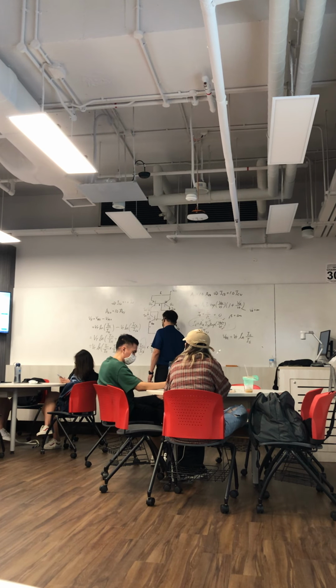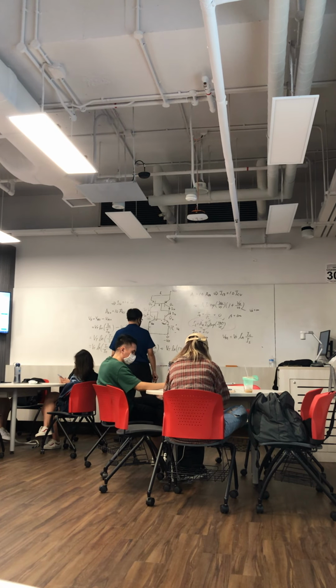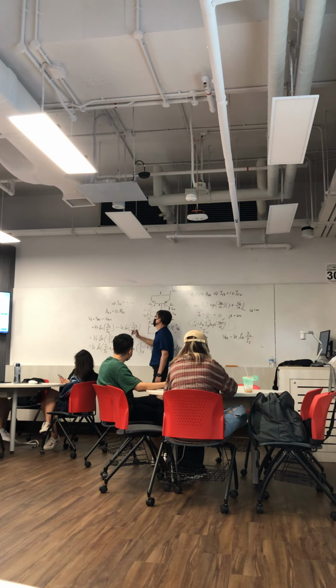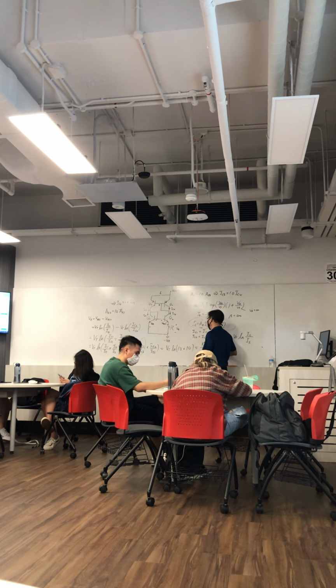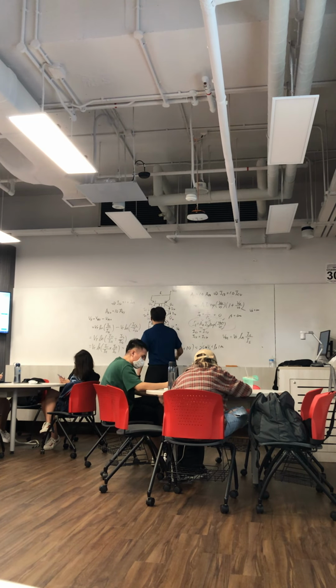So then this will be equal to VT log 10 times, okay? Then IS2 over IS1 is also 10 times. So VT, what is it? kT over q, right? And if you take room temperature, then it's 25 millivolts, right? Times log 100, right? So you can work it out, and you will get the voltage across this resistor.